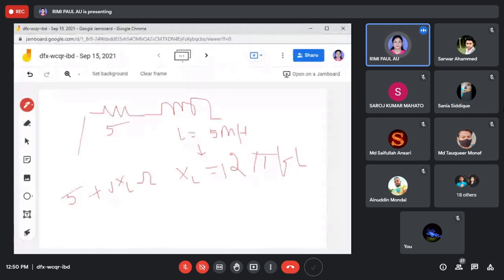Most of the time we forget, and for Xc we also write that Xc is equal to 2 pi Fc, and as per this we calculate, and whatever calculation you do, everything is wrong. So XL means J 2 pi FL, and Xc means 1 by J 2 pi Fc. Then whenever you get this XL and XC, you can add now.